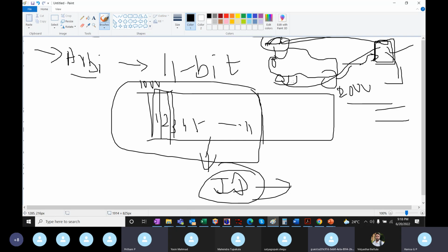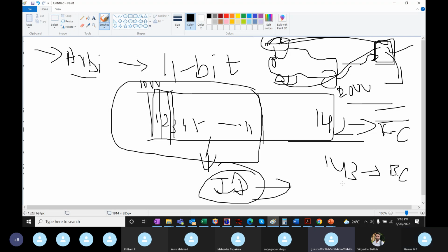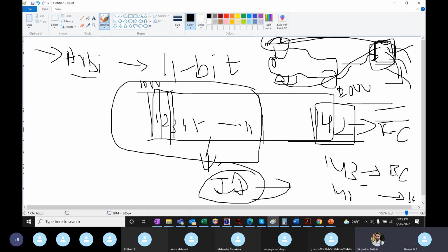To identify which frame this is, we have the identifier. You will be giving a number. If it is 142, it is a front camera. If it is 143, it is a back camera. If it is 145, some side camera. That's how it classifies on the ECU whenever it is providing the output. Whenever you get data from the ECU with the 142 identifier, you will understand it is front camera data.